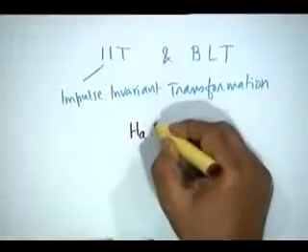In impulse invariant transformation, what one does is take a given analog filter obtained in the same manner, that is, by using some transformation. You transform small omegas to capital omegas. Then you decide on a filter H_a(s), an analog filter.